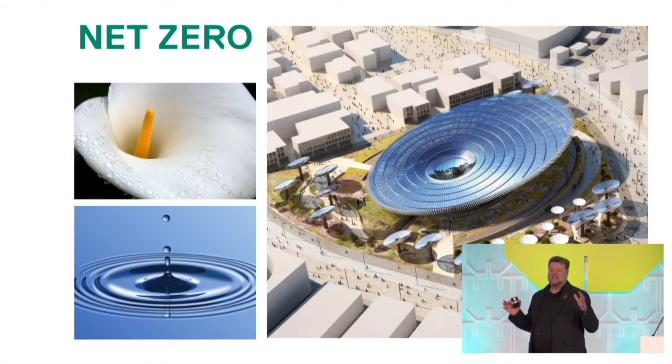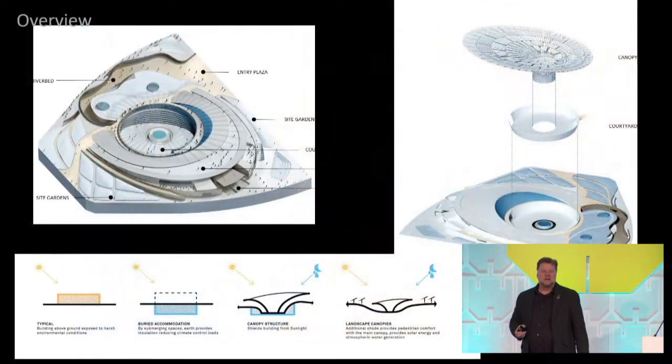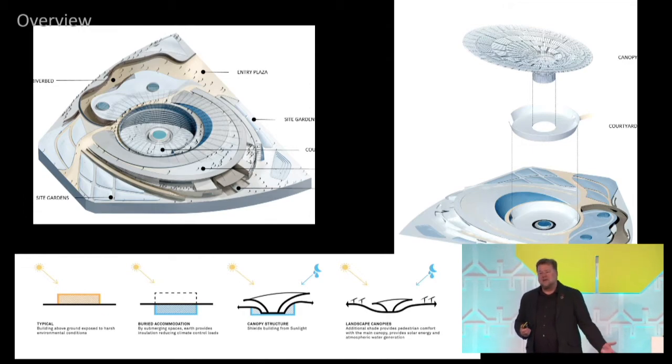So the first thing you do is use the natural resources that are available. The building is actually sunk underground. All of the exhibit area is sunk underground because the whole site was being changed in level. So that naturally heavily insulates a lot of the building. And then the remaining 50% of the building sits underneath a very heavily landscaped roof, so it's also insulated. And then it's bounded by Gabion structures and a very heavy thermal insulation. And then floating over all of that is the canopy.